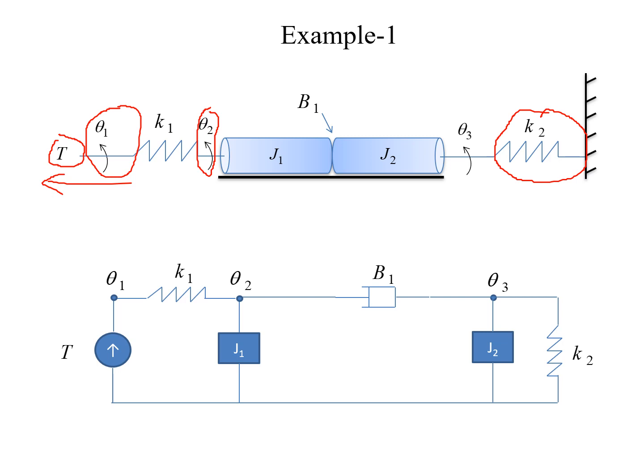This is how a network should be drawn by considering the number of displacements that are experienced in the given system. I hope you have followed this. Now this is very important. Before building any system equation, you need to know the mechanical network that you can draw for a given system.